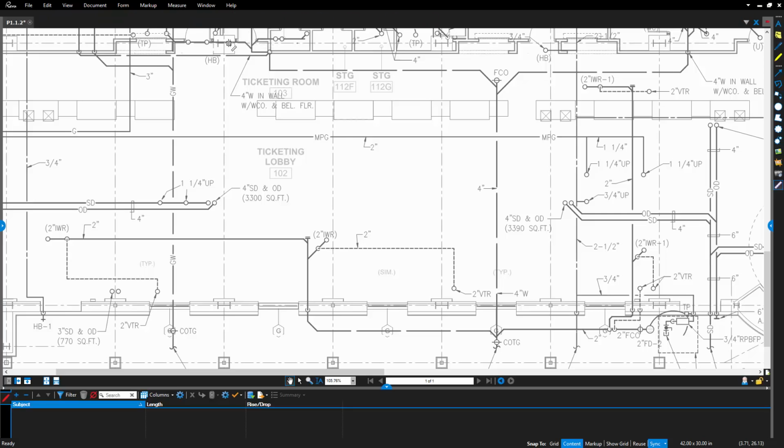To add a polylength, select the tool and click on your starting point. Continue clicking along your desired path, and you can see that each section is measured individually and added to the total as well. Double-clicking will complete the polylength.